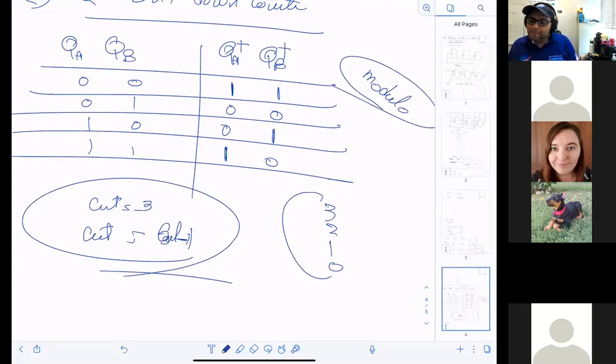But I think he assumed we start at like our first input was 1, 1, and then it goes down. You know what I'm saying? Like it's reversed instead of 0, 0. No. Because, you know, in an up counter, if I'm in 0, where am I gonna go? To 1. Now, because I am a down counter, I start from 3, right? If I am 3, I go where? 2. But because of the order, you got confused. Make sense? Gotcha. Okay.